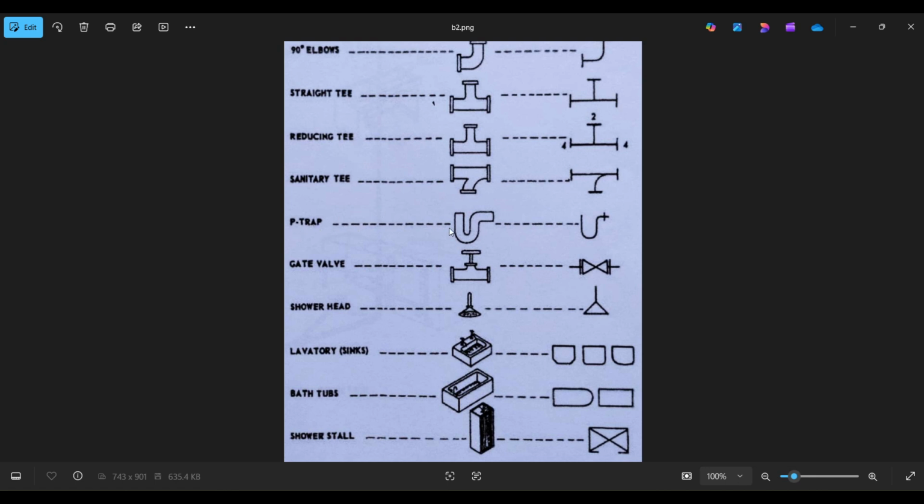And then the next thing we have is a P-trap. So this is a very important thing, guys. You may have seen it in your water closets or in your drains. This is used in order to prevent all the gases we may get from our pipes or our sewer systems from directly being released into our homes. So we may have some sort of a water level here, and that water level prevents those gases from escaping through this route into our homes or our bathrooms, right? We're going to be learning a little bit more deeply about this particular P-trap.